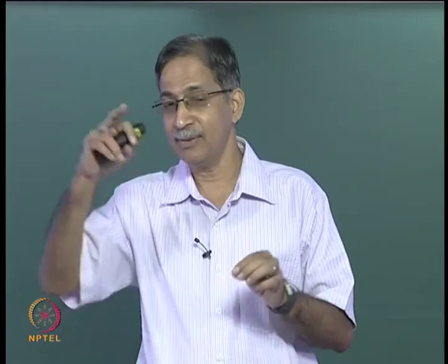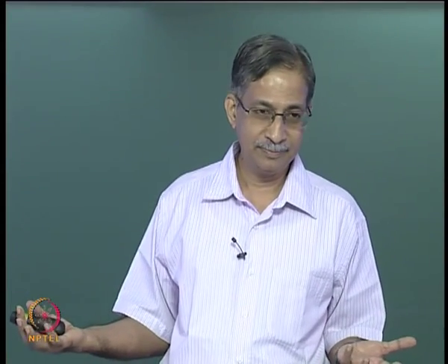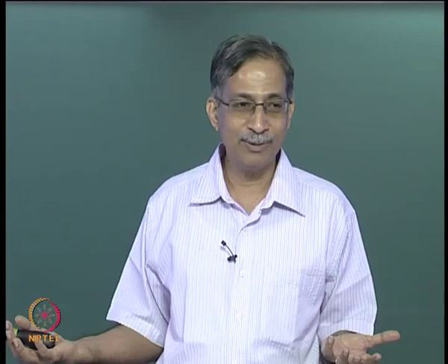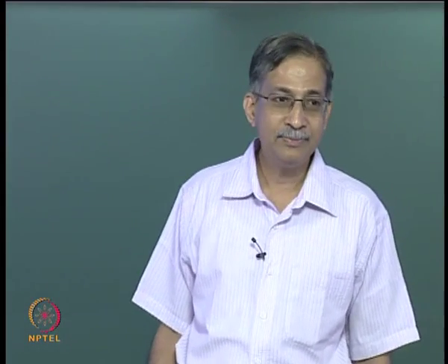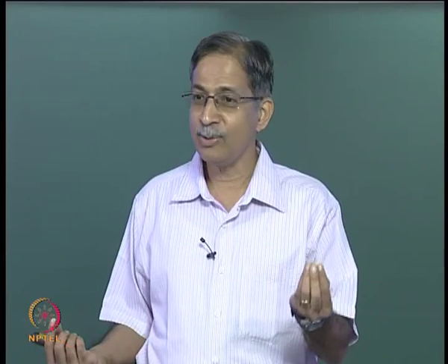But had this structure, for example, been simply supported, what will be the force in all those members? 0. So it's actually not simply supported, it's hinged at both the ends, so there is some restraint. So can you guess what do you think in practice that 990 will reduce to? 100? Let's just hear some guesses. 10 kilonewton. 10 to 20 kilonewton.